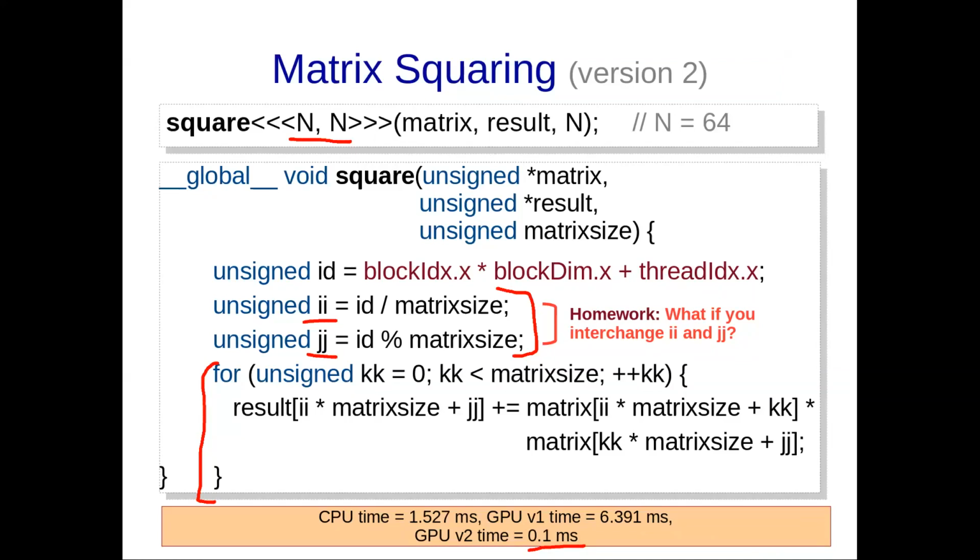There are also some facilities which are provided to all the threads within a thread block. Right? So all these 1024 threads. For example, there is a local cache available to all of these, which is called scratchpad memory, as well as fast synchronization given as a facility, and therefore these restrictions do come into the picture.